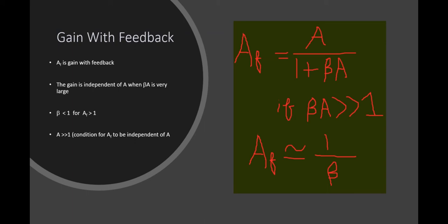For example, in case of 741 op amp IC, it's between 70 to 90 dBs. But when we have feedback, the gain is considerably smaller, usually around 10 dBs. So this is the compromise that we have to make in order to achieve a flat gain.